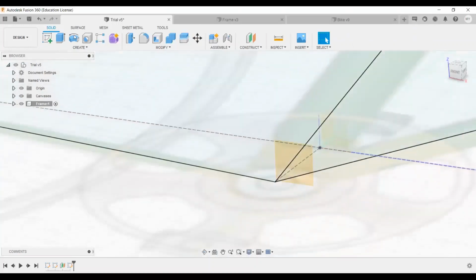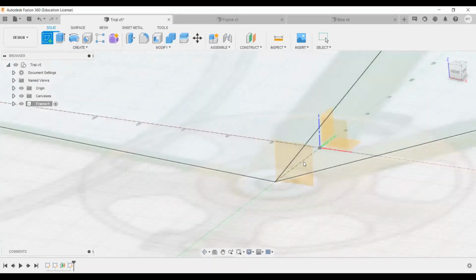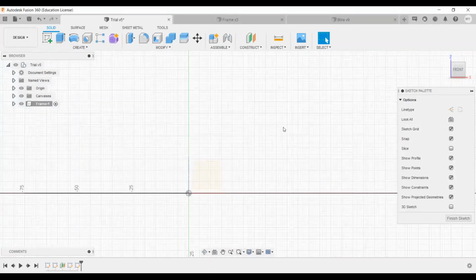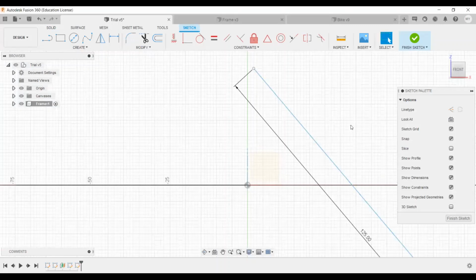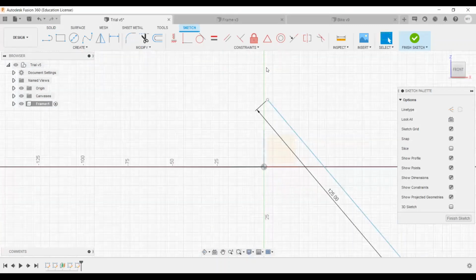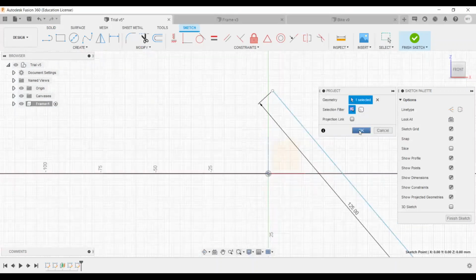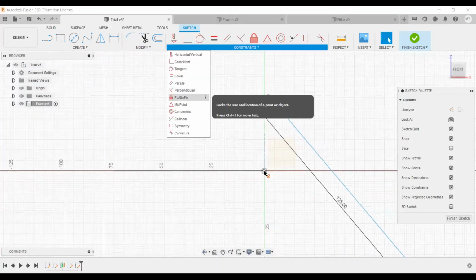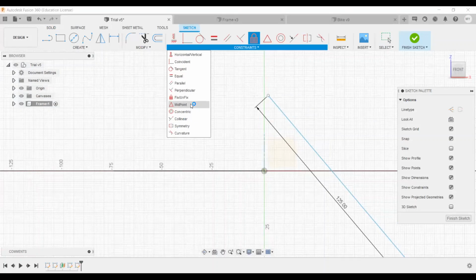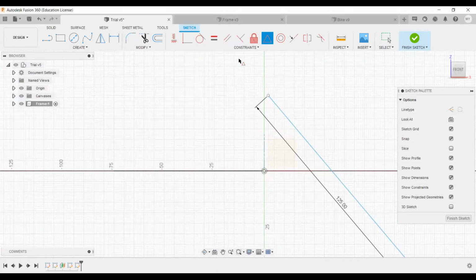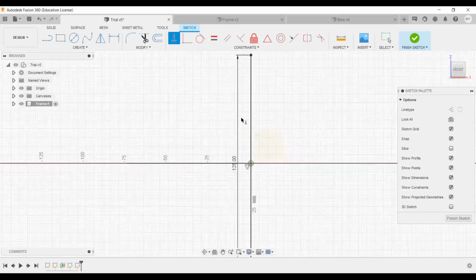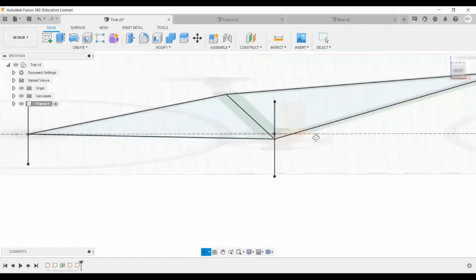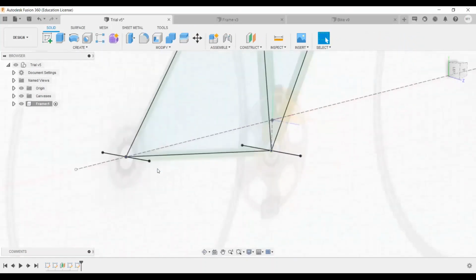Create a sketch through this plane. And I'll draw a line of 125 millimeters. I will project points of interest. It's always good practice to project. And I'll use the fixed constraint, and then finally, the midpoint constraint. I'll just drag it around a bit and make it vertical. So it's defined now. That's great. So now you can see that we have lines for the bottom brackets.